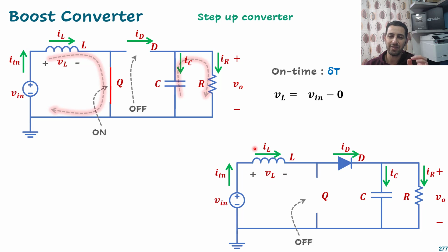So at the moment exactly where we switch off that transistor, we have a voltage here, and that voltage will be like a battery, and we have here a battery, and that is another battery. So you can imagine there are two batteries in series, and both are pushing current toward that point, which forward biases this diode. We can interpret this another way. The inductor already has current from the first duration, okay, and it wants to keep that current in the same direction. That means it has to forward bias this diode, and that diode will be on.